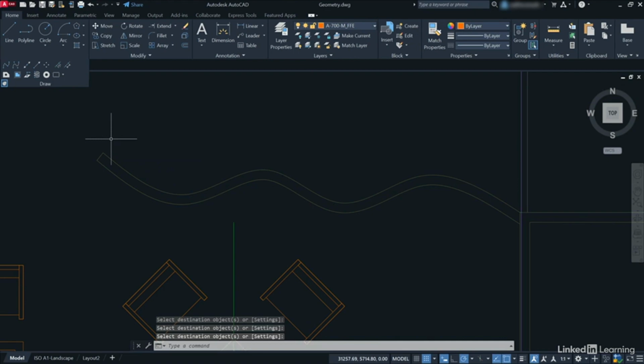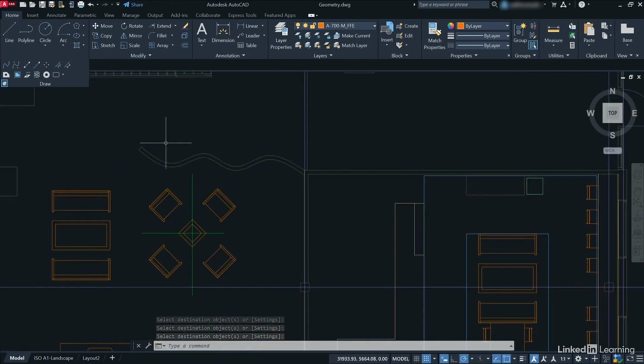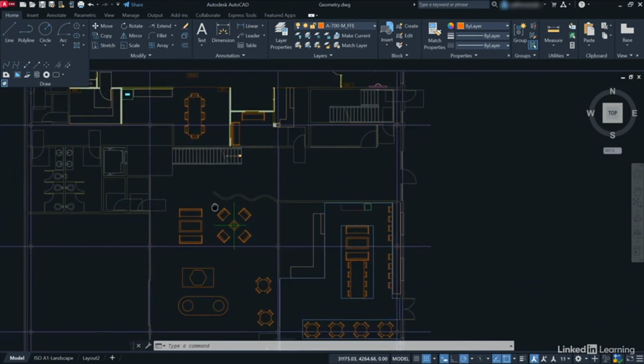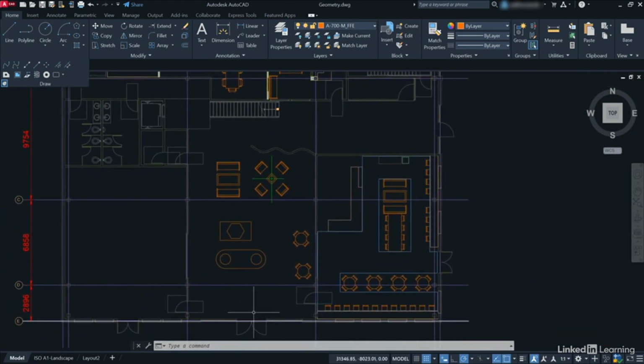So your destination objects are now on the right layer, and they're on the same layer as the internal walls. But what you've done is you've created a little boundary here, a little barrier that kind of blocks off the main corridor here where the stairs are from the little atrium seating area and the opening of your floor plan, like so. So people come in the main doors here, see our new tables, walk through, and you can see there's a little bit of a sort of barrier there that you've created using a spline. So what we'll do, we'll unpin our little draw panel here. That floats back into the ribbon, and you've now created a polyline, a polygon, and some splines as well.